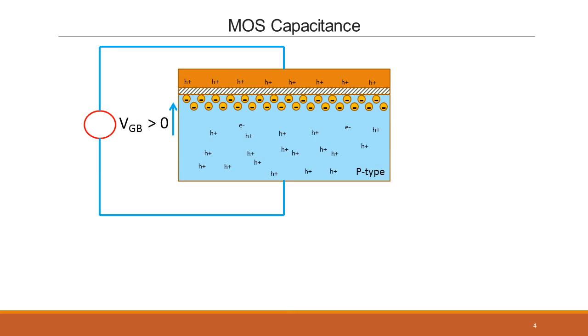Now, what happens if you increase the voltage even higher? So that is the gate, you take it even higher now. Right? At some point, at a voltage called Vs at the surface, when the voltage at the surface here reaches a specific value, right? Okay. We'll just draw what happens to the voltage. The Vs value actually keeps increasing as we increase VGB initially. Okay. Then if you increase it even further, okay,